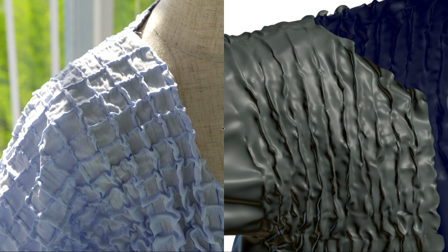Now, these simulations focused solely on horizontal shrinkage, while the left-hand side also has vertical shrinkage, which is why the final result did not perfectly replicate the physical output. However, the primary intention was to test whether Houdini could be used to simulate such interactions and provide reliable feedback for the physical designs. In this regard, the project was successful.